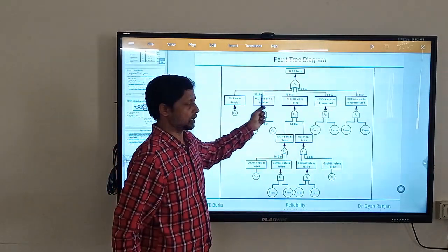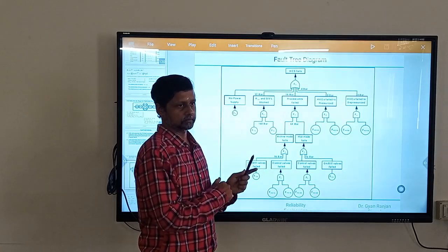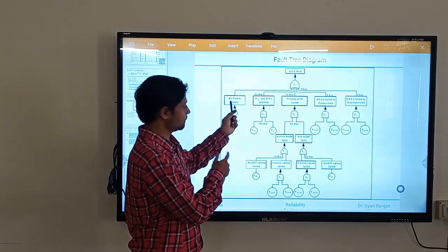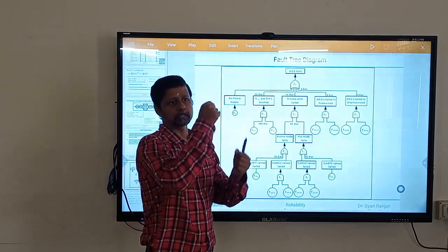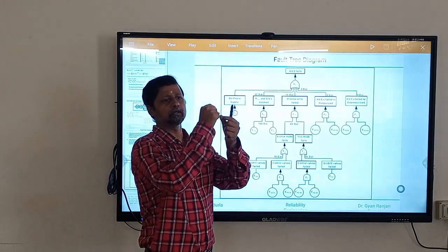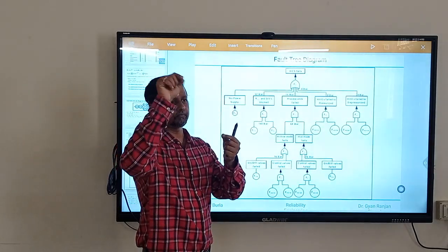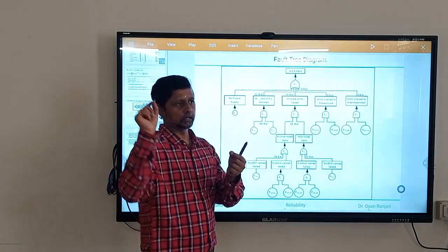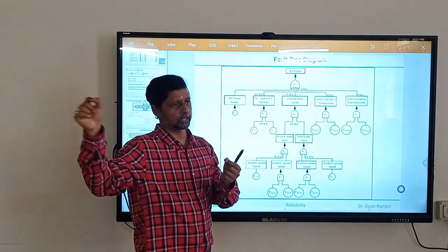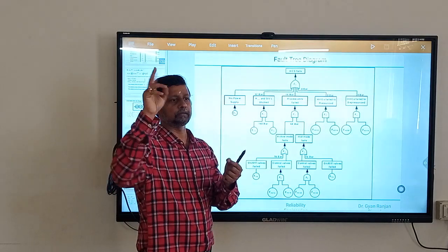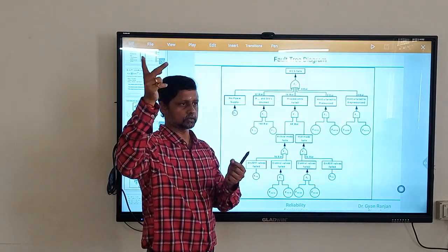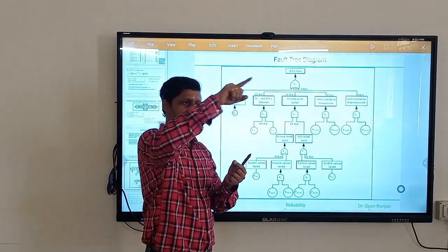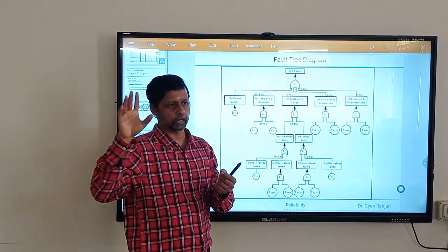So now it will be in parallel. Dual of this. So dual of the connection. If you remember that circuit theory, when we do just a small exercise, if RLC is connected, we prepare a dual circuit diagram. So R's complementary is 1 by R. C and L are replaced by each other's values. If RLC is in series, then we connect it now in parallel.